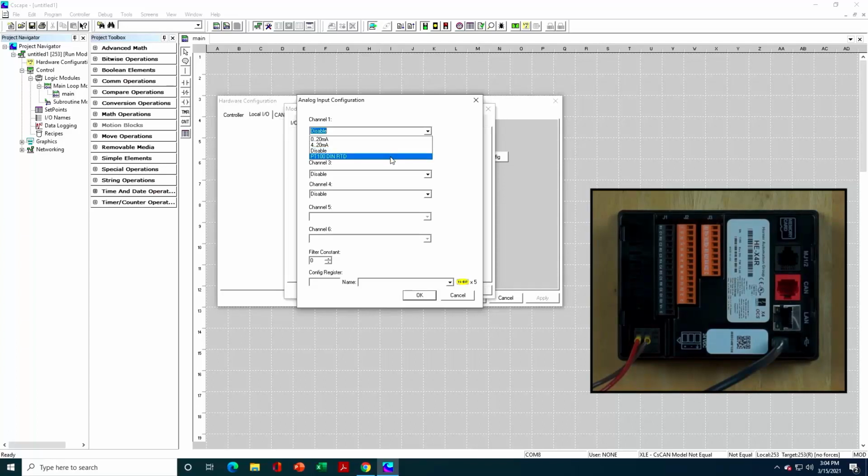And then finally, you can select RTD PT100 on each channel. Now keep in mind, with the Micro series, this is a limited range for RTD. Normally with RTD PT100s, the full range would be, let's say, -200 to +850C. But with the Micro series, because it is a budget line, you are limited to a temperature range of -50C to +200C. But for a lot of applications, that's perfectly fine.